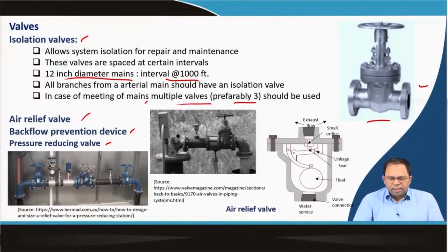You can see the design of air relief valves over here. There is a float. When there is water pressure, this float rises up, and then this opens up, and this extra air over here can be released. This is the actual image of this air relief valve.